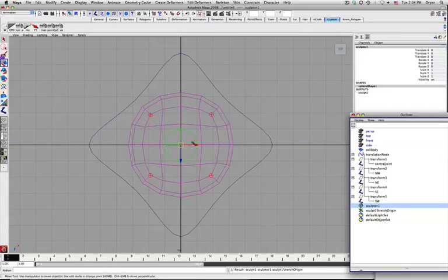Create. I'm going to do this 4 times and then point constrain the sculpt deformer, the sculptor here, to each of these joints. You see the sculptor also has a locator that's called the sculpt stretch origin. And all this does is tell Maya which direction the sculpt should be happening in.